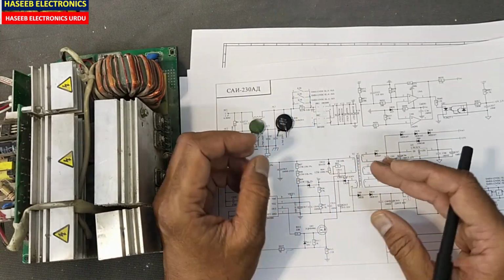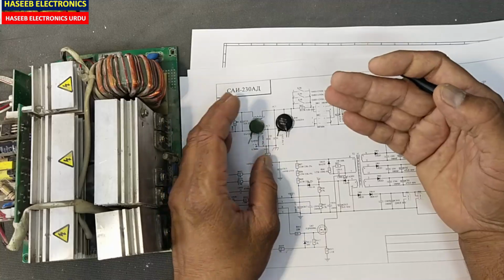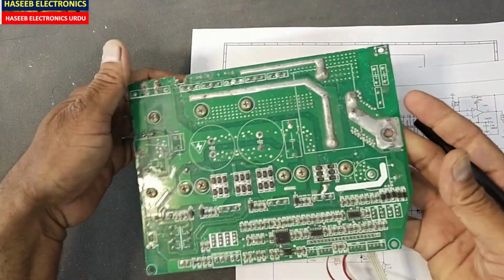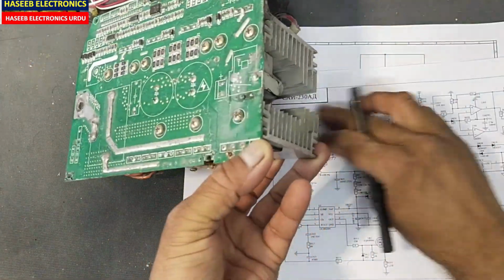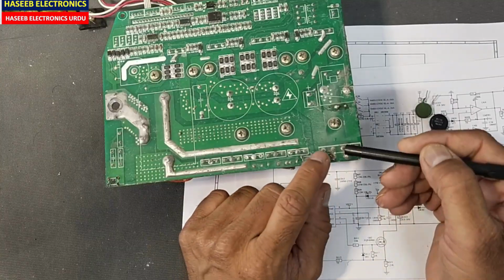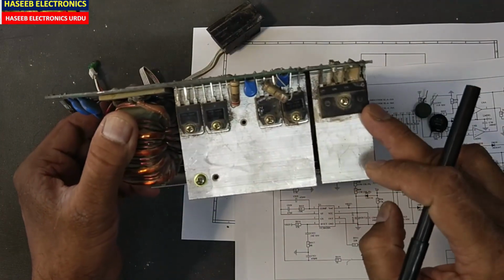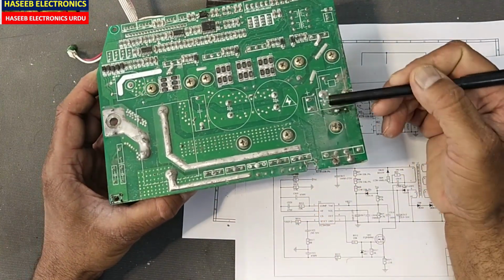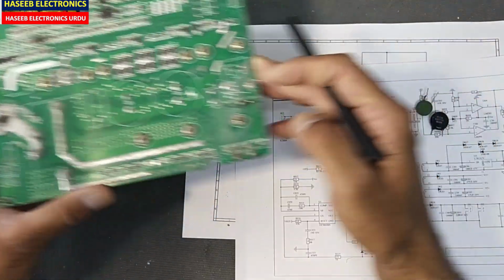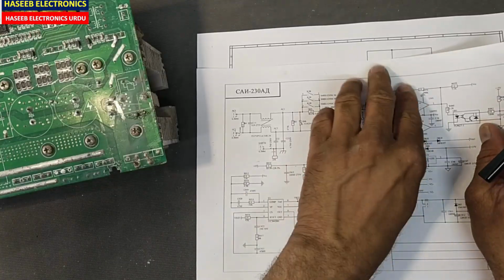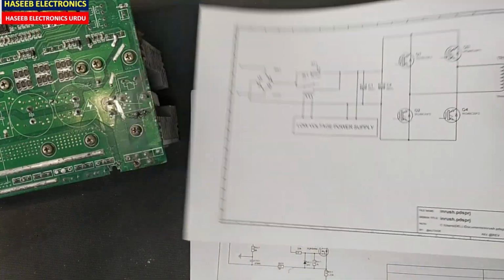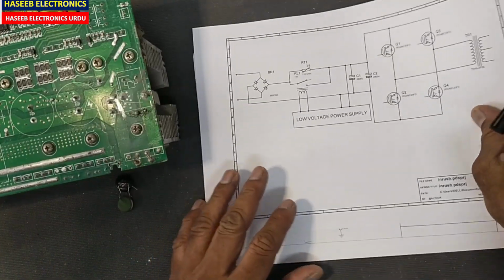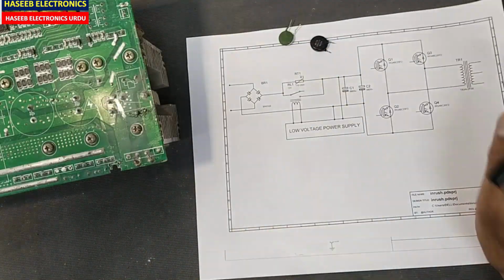Basically it is a type of resistance which is used to protect against the inrush current. When we see the practical circuit here, we have a bridge rectifier, that is here. Here is the input line terminal. After the bridge rectifier there is a component that is used in series with the positive line. I simplified this diagram to understand it easily, and then we will see what is the reason for its damage.